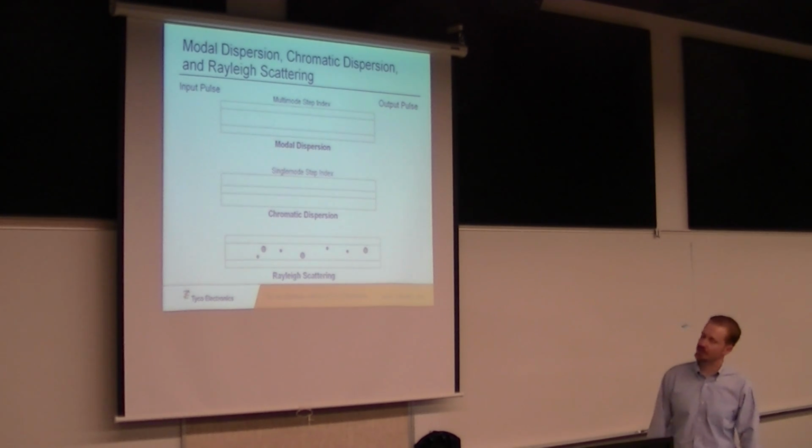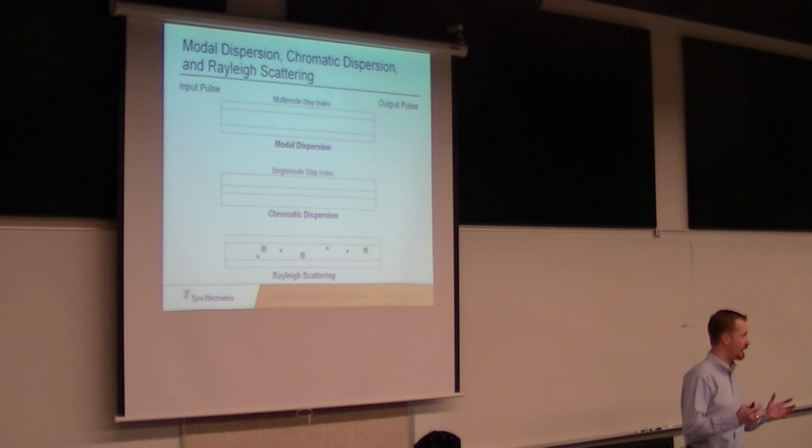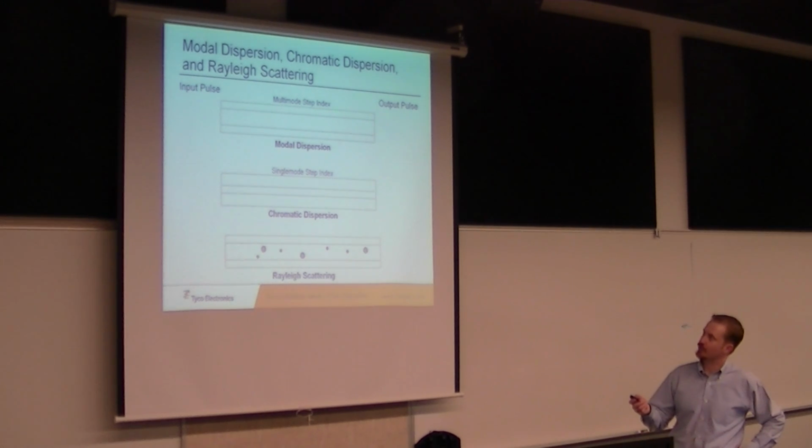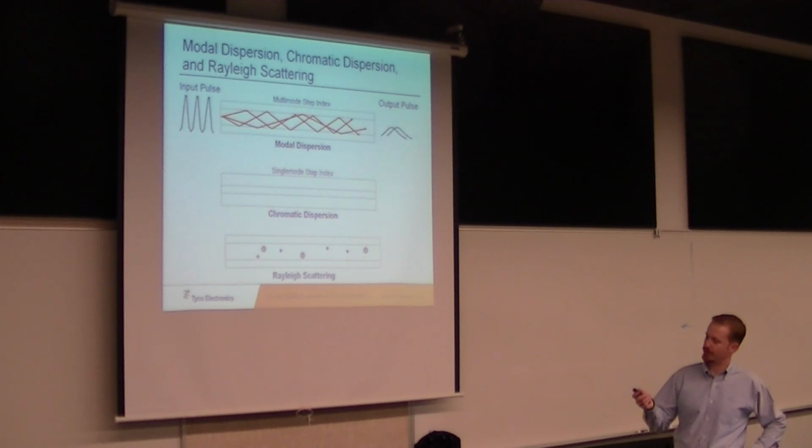There are things, it's dispersion. Dispersion means to break up and go away. So some things that happen with fiber optics on multi-mode fiber, especially multi-mode step index fiber, if I put an input pulse, I have three signals going in. These three conversations go through here. And in step index, they all arrive at different times. You have that pulse spreading I talked about.